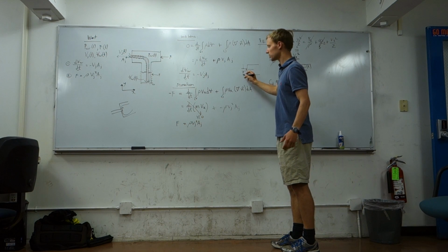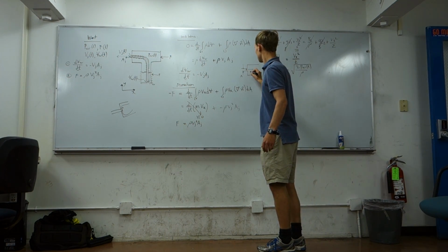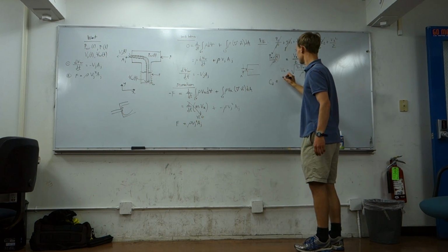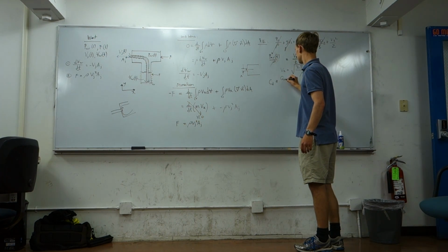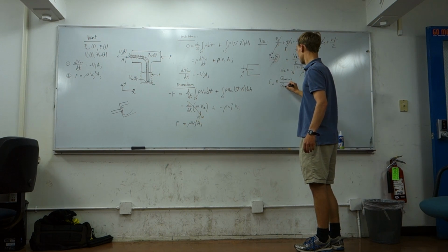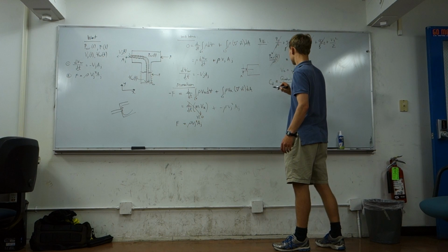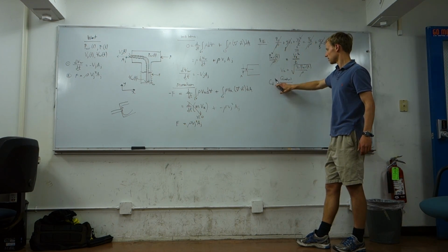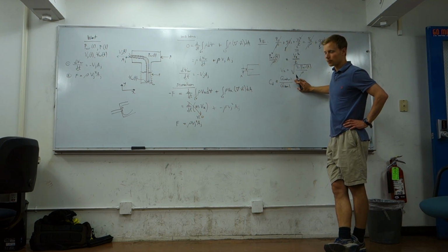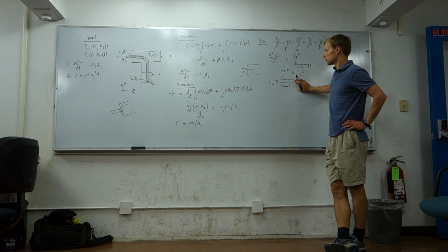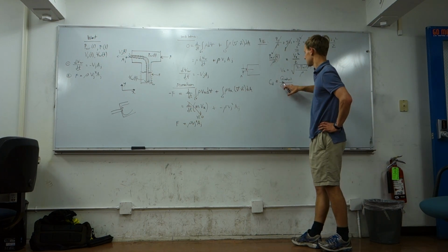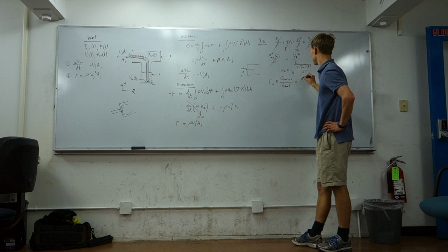It's defined for any sort of contraction or expansion, as the ratio of volumetric flow rate in the actual real world, or what it would be if it were inviscid, so in this region here. So for a perfect nozzle, you have no losses and you get the ideal volumetric flow rate. Of course, we have some losses, so it's going to go down. We know that the area in both cases are the same, so this just becomes V actual over V ideal.